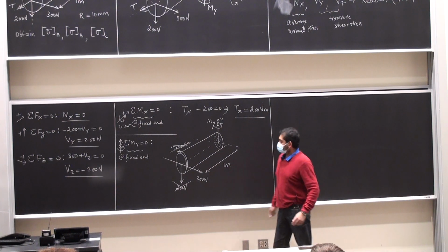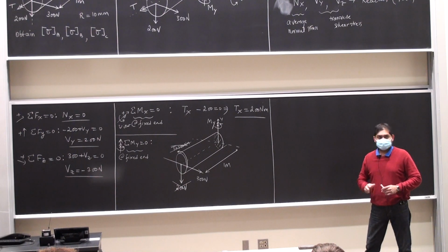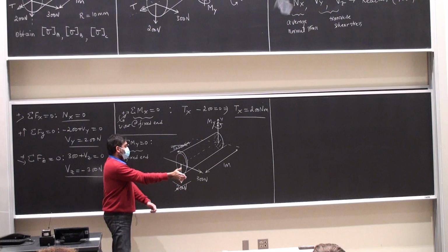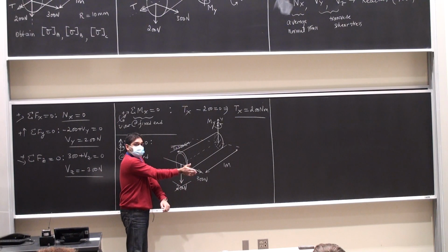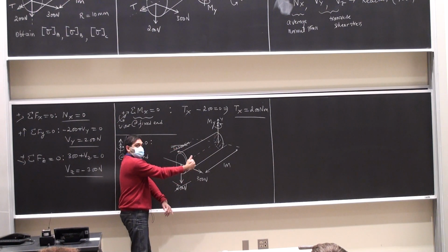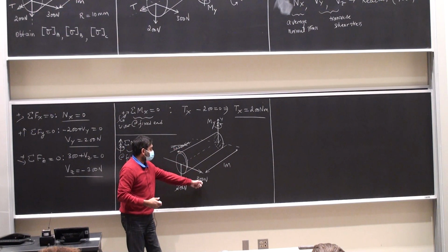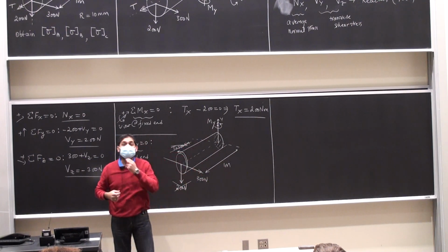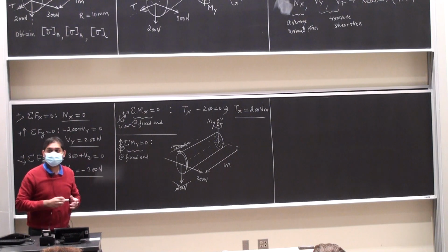So this guy is the culprit, 300 newtons. Right hand rule. Fingers of my right hand aligned with the force of 300 newtons. My palm is facing the y-axis. You see there? The y-axis. I curl my fingers. This 300 Newton force multiplied by a distance of 1 meter is going to cause a rotation about the positive y-axis.